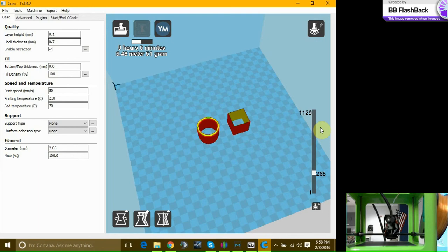find out if you have calipers on you that it's off by about 14 thousandths of an inch. This is due to shrinkage or the belts being loose or some sort of mechanical error or software error.